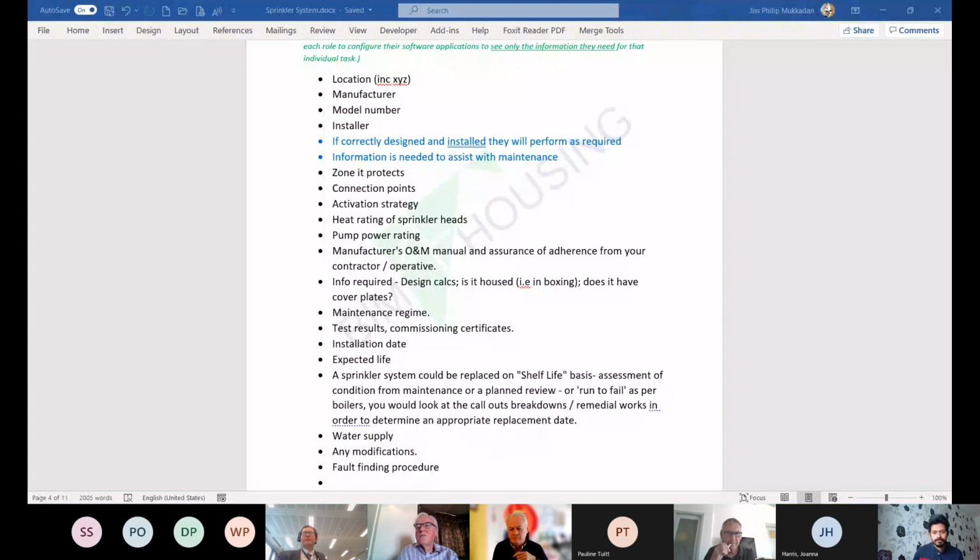Yeah, basically, when CPVC started going into residential developments, the mastics, this all comes back down to the fire stopping conversation the other day, the fire stopper comes in and puts all their general mastics in it. Well, unfortunately, the CPVC and the mastics they were using, and it was all to do with graphite based or non-graphite based, was basically attacking the plastic pipework, and most of it was Blazemaster anyway. And literally, it just caused the plastic to stress fracture pretty quickly. Yeah, that can impact on sprinklers, can it? Yeah, I mean, you lose the pipe.